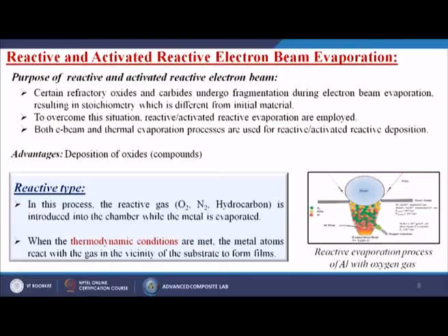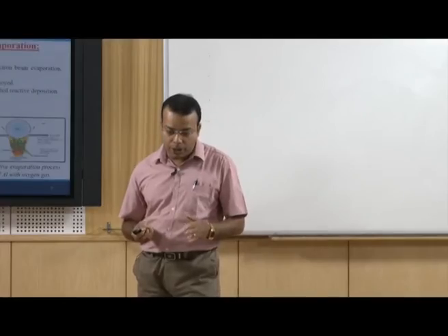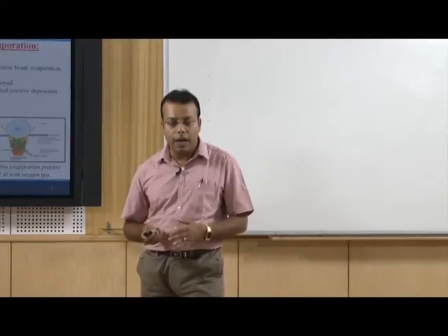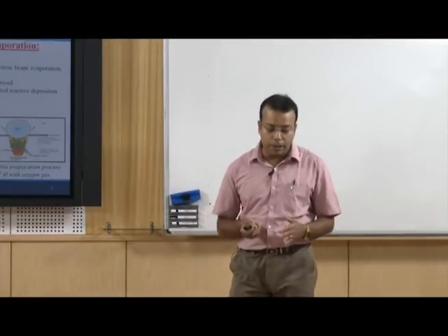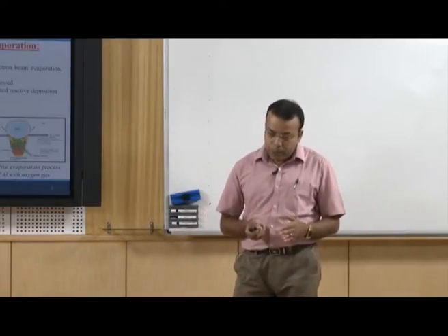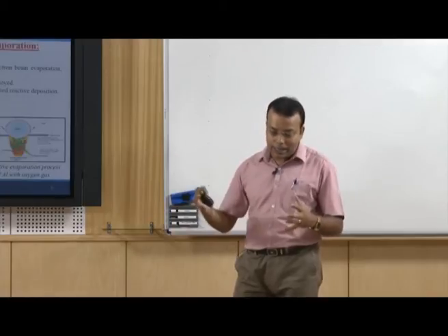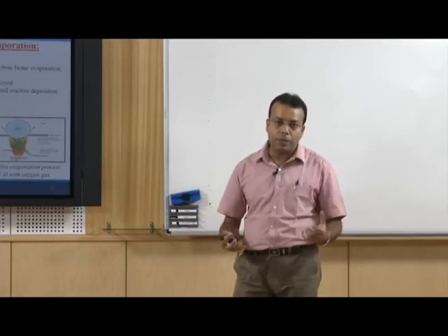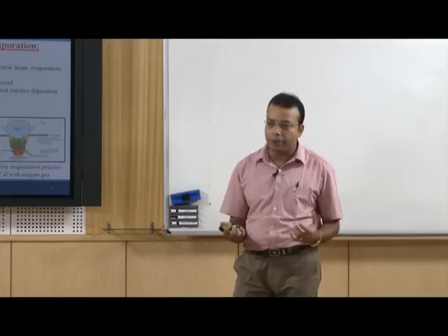To overcome these situations, reactive and activated reactive evaporations are employed. Both E beam and thermal evaporation processes are used for reactive and activated reactive depositions. So first we discussed thermal evaporation, then we discussed E beam or electron beam evaporation. So these techniques are combinations of thermal evaporation as well as electron beam evaporation, right.